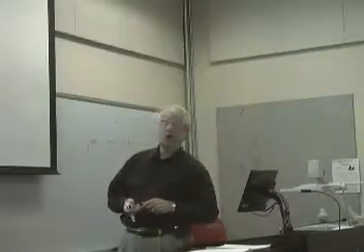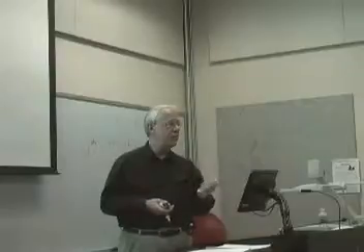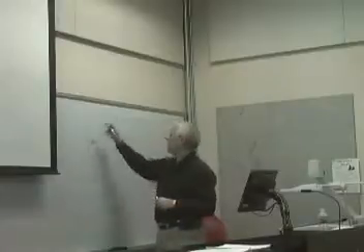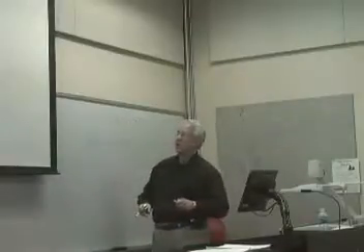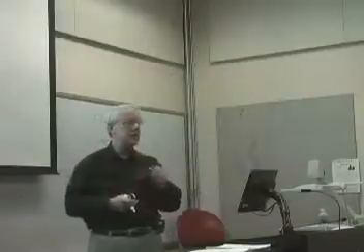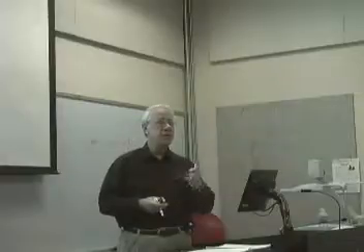Point is that you can solve for the shape functions for these various types of elements. If I want to go to quadratic, what do I do? Remember, here's node 1, 2, and 3. All I have to do is add a mid-side node. If I have a mid-side node, I now have a quadratic per leg. 1, 2, 3. So I have 3 legs. So now my matrix per element is 6 by 6, not 3 by 3. What's the relation in going, how many 2 by 2s in a 3 by 3?